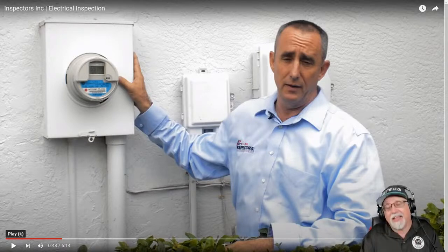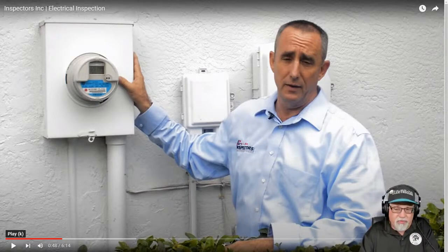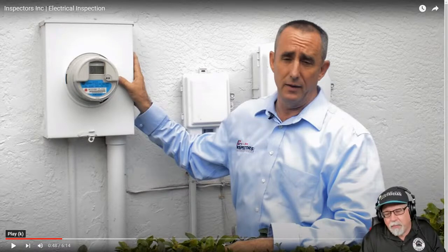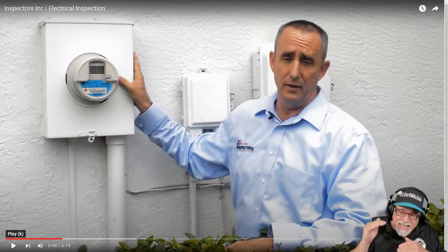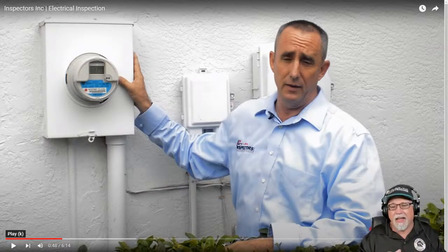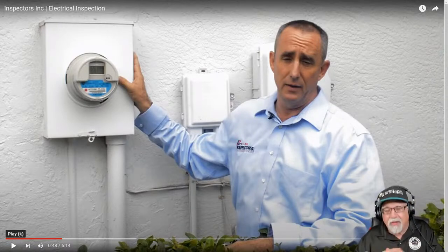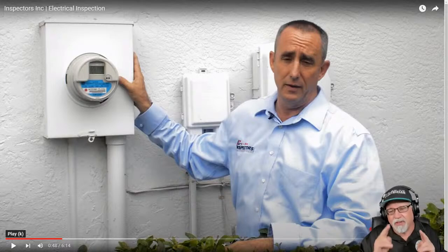Those ground rods have to be driven. If they hit rock, they can go at 45 degrees. If they hit rock again, then they can be laid in a trench. Okay. And all those rules are found up in the code. So point being is, they also would have 2 rods. They'd have to be at least 6 feet apart. The rods themselves have to be 8 feet long, and generally they have to be driven. You have those other allowances, but you have to start out by trying to drive them.